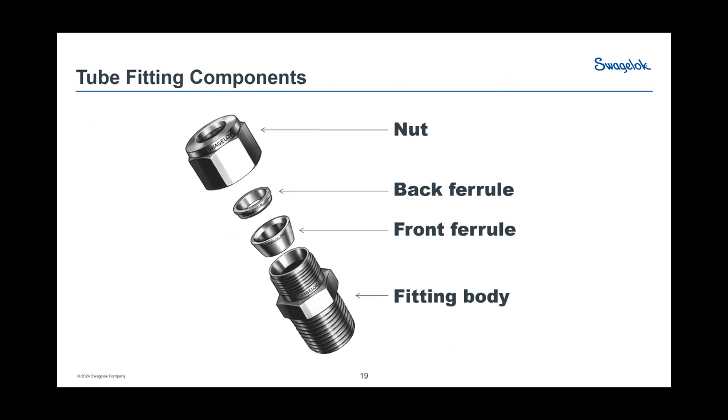There can be certain applications in production, specifically steam methane reforming, where there are going to be big pipes involved, and that's just the nature of how that system works. But once you get beyond that, everything from transportation, injection into natural gas lines, on-vehicle, virtual pipeline trailers to bring hydrogen to stations, all the vehicles, the most appropriate fitting technology is a 2-ferrule fitting.